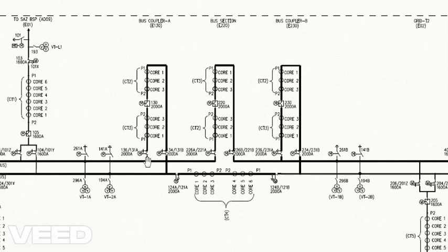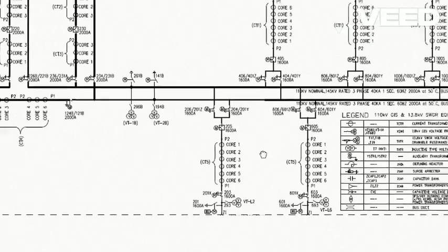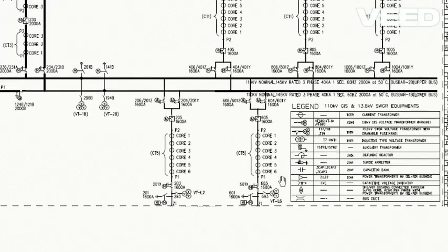During the maintenance period or during load shedding or load management, these bus couplers and bus sections are used according to the load requirements. So this setup gives the operational and maintenance team flexibility to shift the loads and manage the loads under normal or abnormal conditions. So guys, this is the brief introduction of the single line diagram.